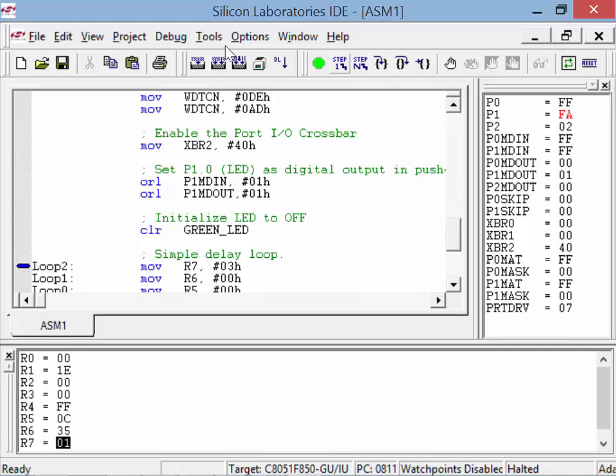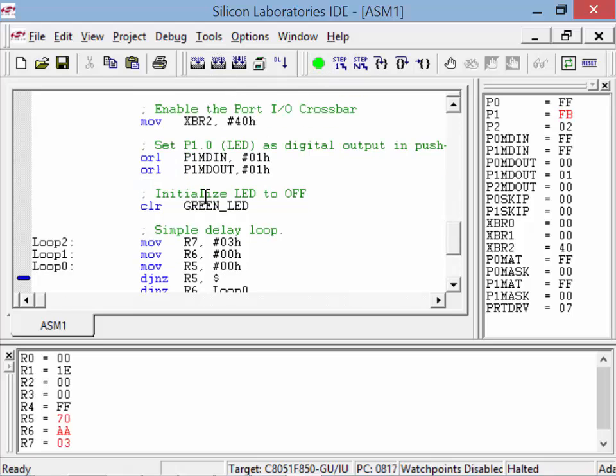you can see as we clear that LED. Now, actually, remember that when we write a 0 to it, we actually turn it on. So actually, initialize it. This actually means on right there. So I just turned on the LED, and it's a red LED. It's not a green LED. Again, I got there. And I can run this program, and it'll just keep blinking. Everyone can see that it blinks. I can stop this here.